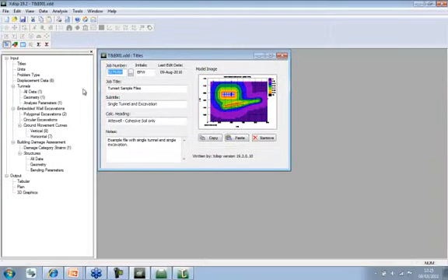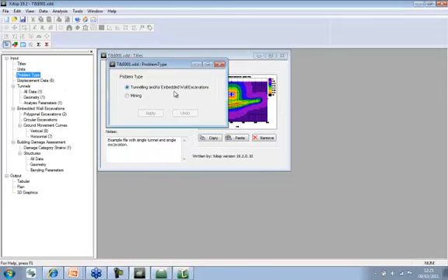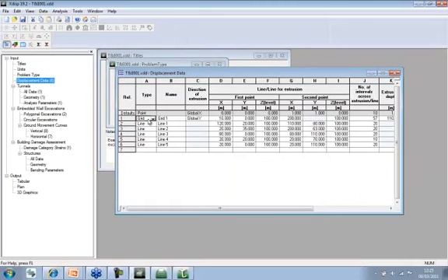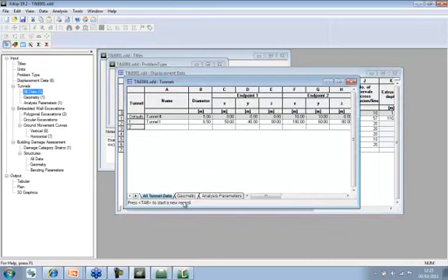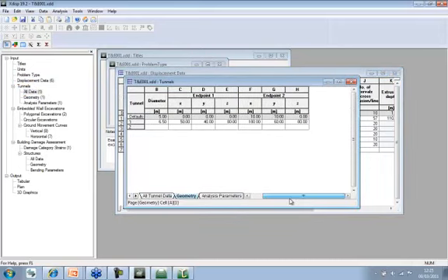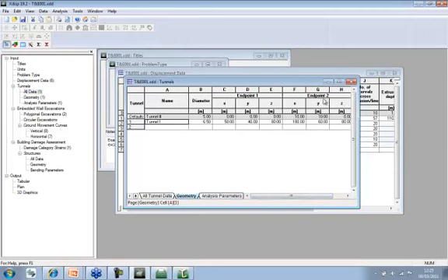Here we've got an example in XDisp where we put a tunnel next to an excavation, and here the problem type is a tunneling or embedded wall excavation. We've put our displacement data in, so I'm interested in a grid which is at the surface of the problem, and a number of lines, maybe associating with the tunnels, maybe associating with utilities close by. And as you can see, the tunnel data is shown here. We have the geometry of the tunnel, and there's one endpoint and two endpoints here, but you can have a number of endpoints if you prefer.